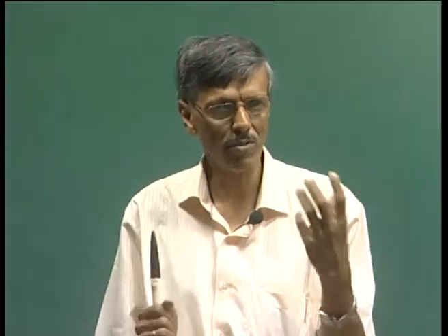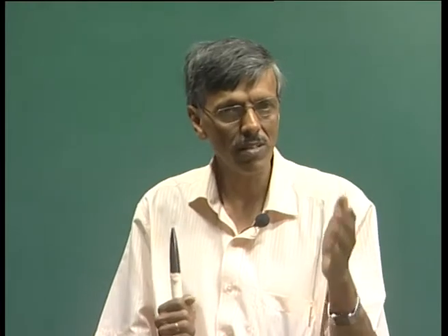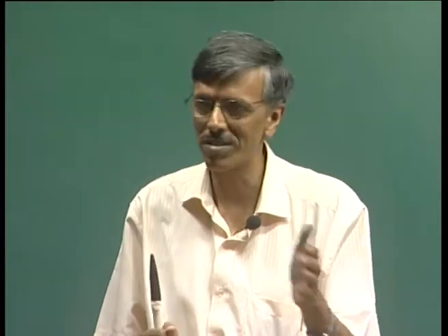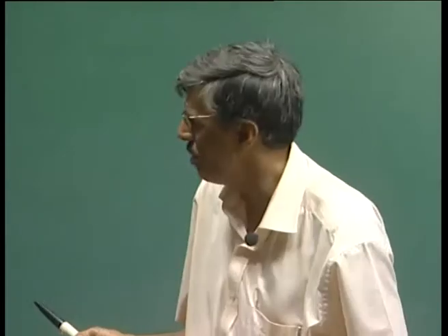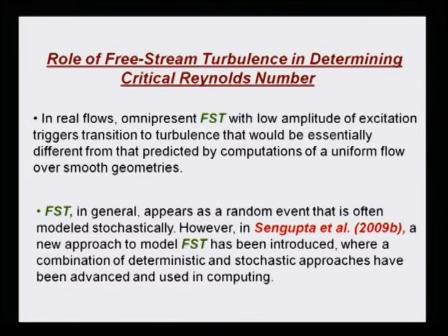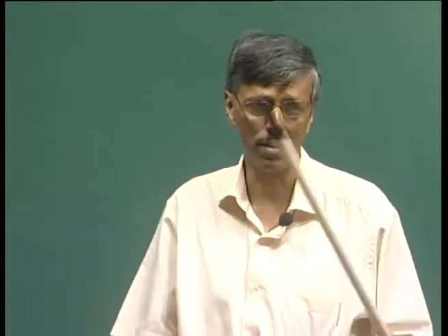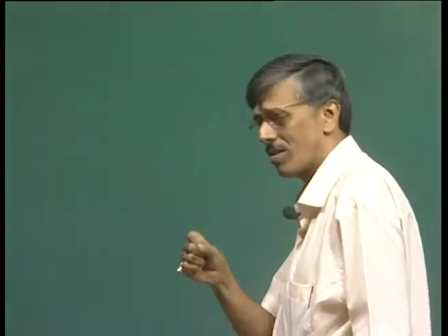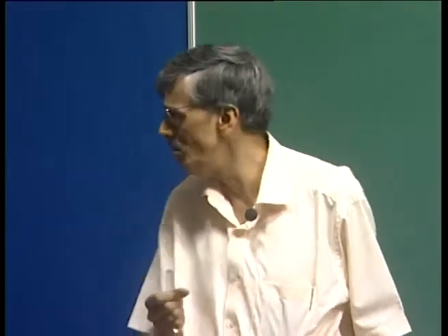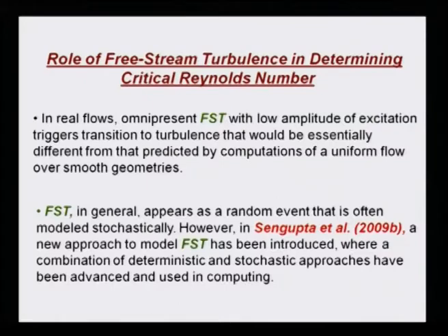In designing a wind tunnel, what we try to do is break down these larger vortices into smaller ones, and that is what you see. You have all those honeycombs and screens doing it for you. So, basically what we are talking about in terms of background disturbance are the remnants of those large eddies which originate in the size of the propeller that is driving the airstream. But through the action of the screen and honeycomb, we break it down into smaller ones. So, that is what we get as free stream turbulence.